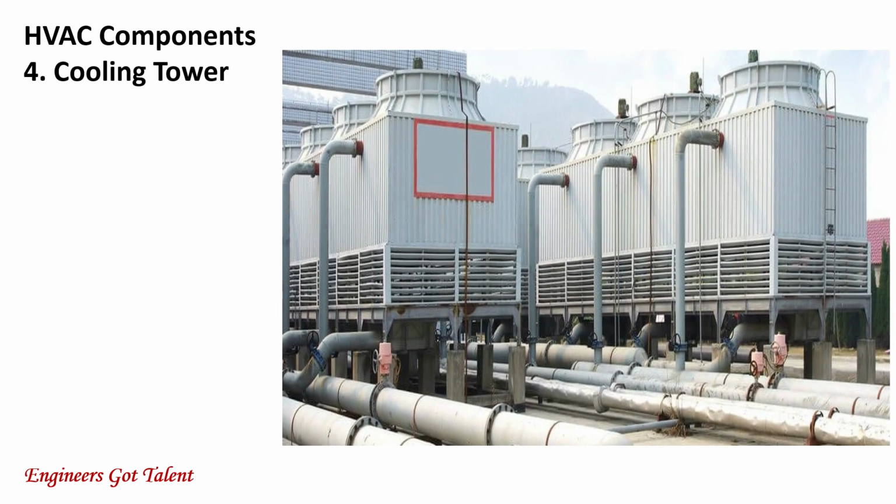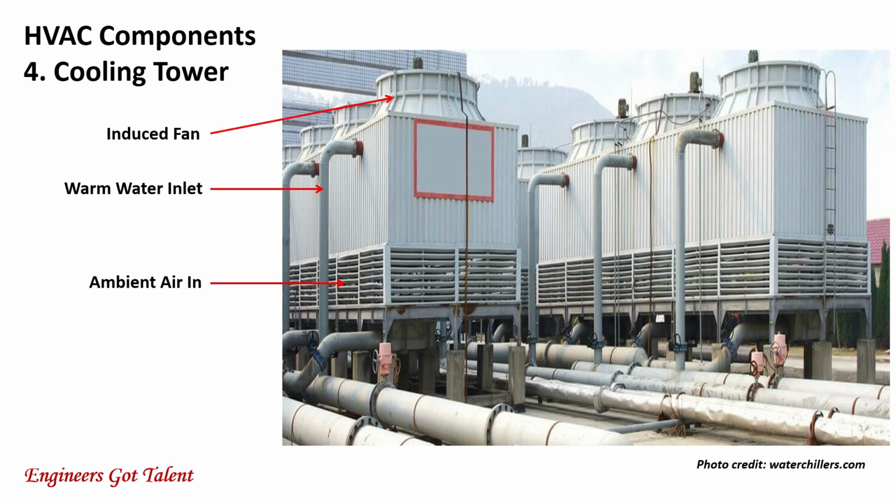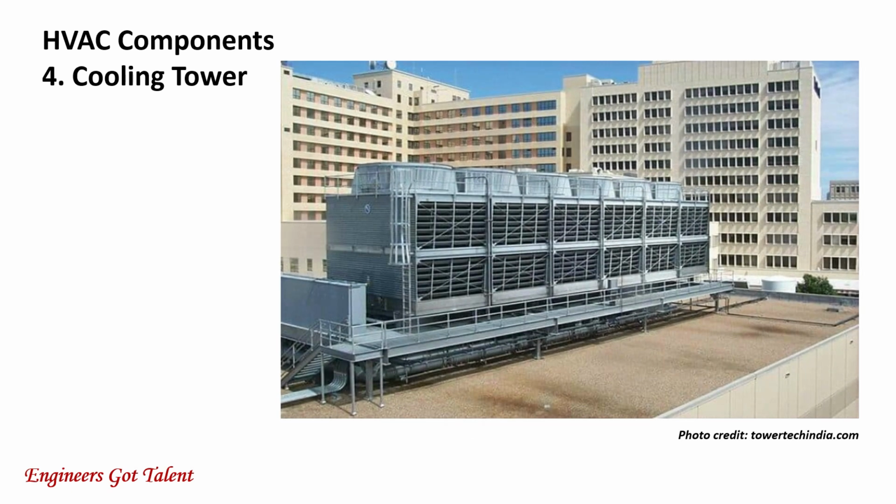This is a picture of a cooling tower. Warm water from the condenser enters at the top of the tower. Ambient air gets in contact with the sprayed water using an induced fan. The warm water cools and is collected at the bottom of the tower. Another picture of a bunch of cooling towers on a large capacity HVAC system.